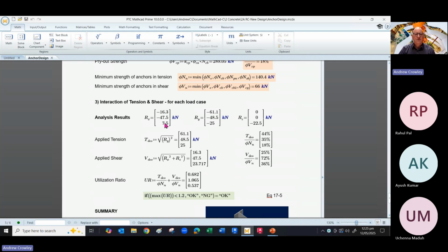So we've derived these arrays from our matrix, which was basically the table above, to give us our Rx, Ry, and Rz. And remember, multi-frame talks about linear forces in terms of Rx, Ry, and Rz. In our case, Ry is upwards, and for these load cases, everything's in tension, because when you were designing that anchor, we're really looking at the tension cases.